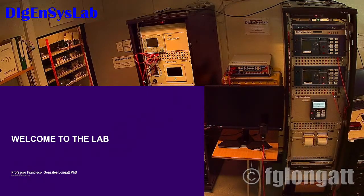Okay. First step, definite time, 0.3 seconds. We will see the signals, yes? And the SCADA, we will see the signals, okay? And it's a good idea that we make comments about this, so that you can see how the voltage goes to zero. No, this is the current. The voltage decreases during the fault, and after the breaker opens, the current goes to zero. Very good.